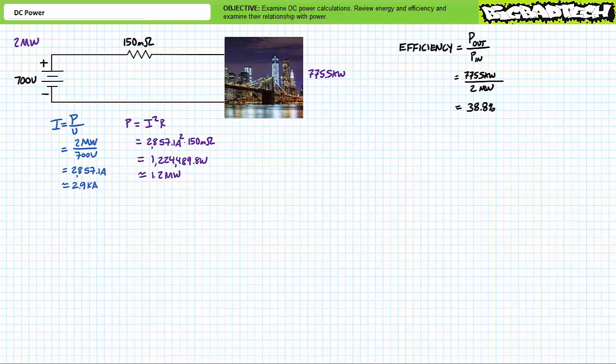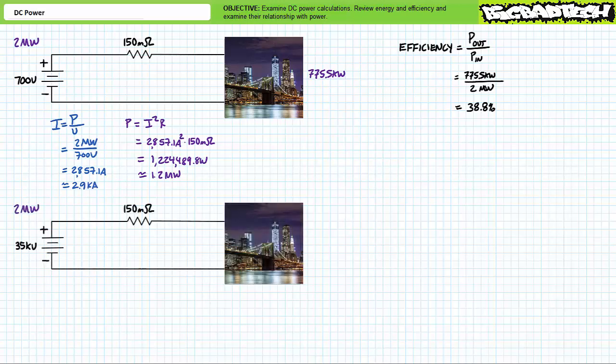High current results in massive amounts of line losses, and substantially less input is directed towards useful output. It is largely for this reason electrical power is generated and transmitted using AC rather than DC. AC electricity, in contrast to DC, allows for the use of a device known as a transformer that steps up voltage at the same time stepping down current, and vice versa. We'll examine AC power and transformers in later lectures.